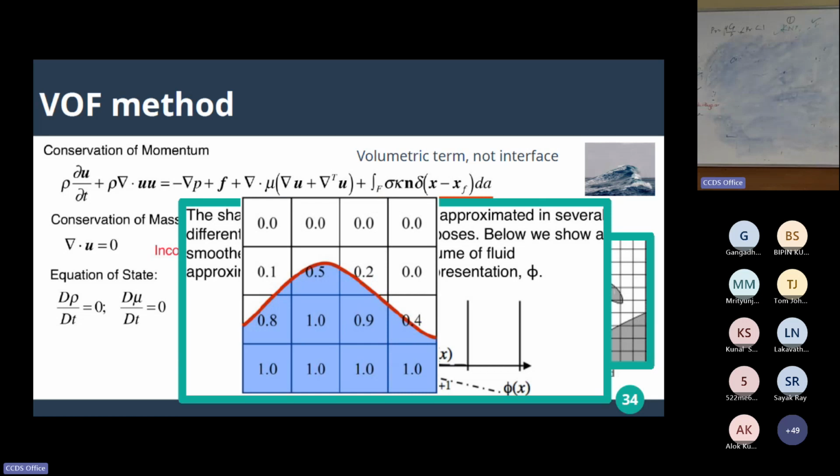So usually when one solves the transport equation, they get numbers like 1, 1, maybe 0, 0, 0, indicating that yes, liquid is present in the mesh. But wherever the gas-liquid interaction is happening, you will get some numbers in between 0 and 1. Based on how clearly you fill those numbers, one will be in a position to get this red kind of interface. Though at an abstract level I might show some red line, where exactly do I need to put that red line to capture the interface?